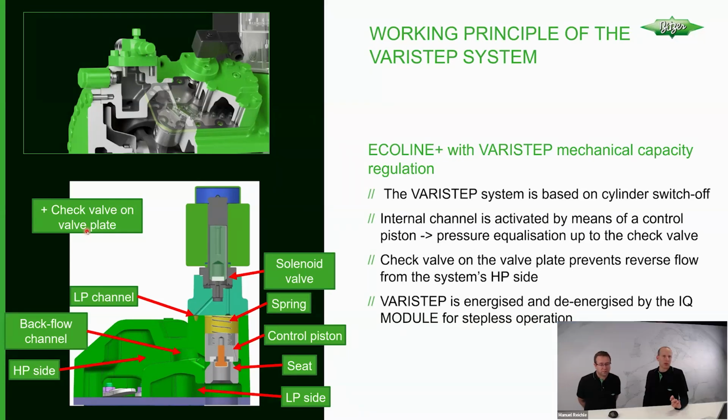That is something I will come back to later on, where we also show our application limits. Within what we publish, this is tested and verified, but you are completely right. At lower pressure ratios, at some point, the valve plates no longer function properly. A compressor is not a pump being able to do really, really low pressure ratios. That is why we also publish where it can be used and where it should not be used.